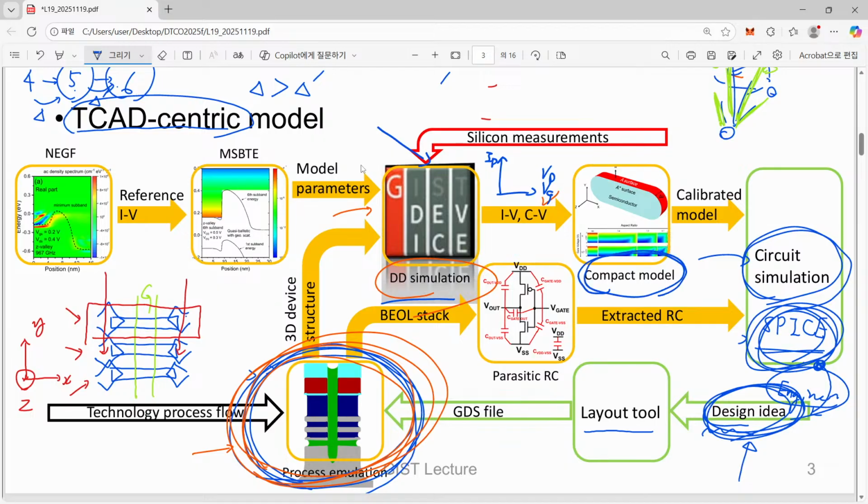And what is a compact model? Simply speaking, it is a more elaborated version of this expression. I'm exaggerating a little bit, but roughly speaking, it is like a collection of terminal current expressions. When you apply gate voltage, you can get drain terminal current. Of course life is not that easy even for the compact model.